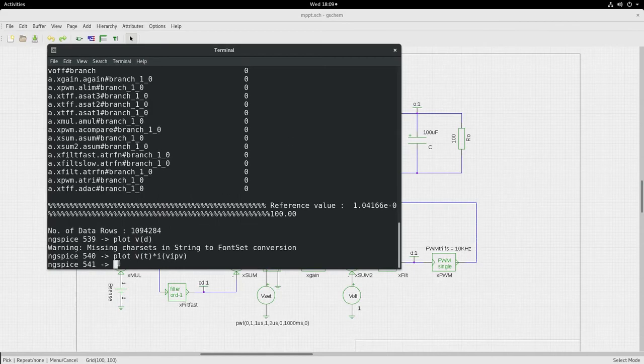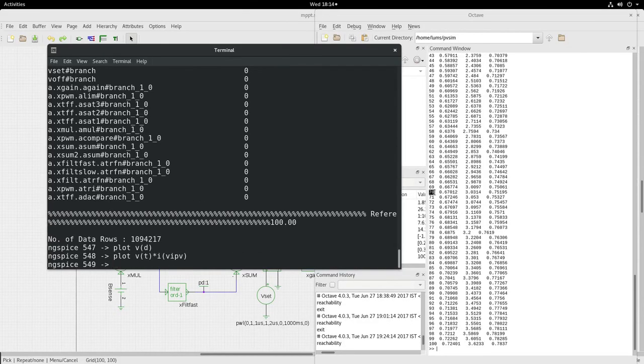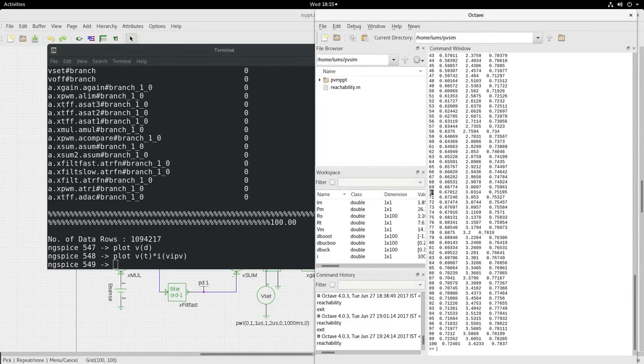What we shall now do is change the value of R0 from 100 to some other value. Let us choose now R0 of 70. For R0 of 70, the corresponding duty cycle is 0.75, which will work out to be 0.75 into 2 minus 1, around 0.5, as the value of the voltage input to the PWM carrier.